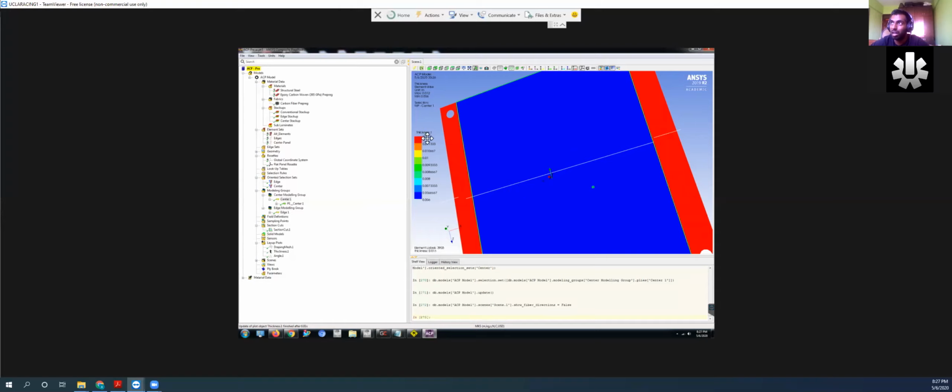So this essentially shows that there's a color scheme for the different thicknesses. So remember that we said 2 millimeters for each ply, and the edges we put an even symmetry, and we input 3. So that means you should get a total of 6 plies on the edges. 6 plies times 2 millimeters equals 12 millimeters. So if I look on the edges, I have 12 millimeters worth of carbon fiber on the edges.